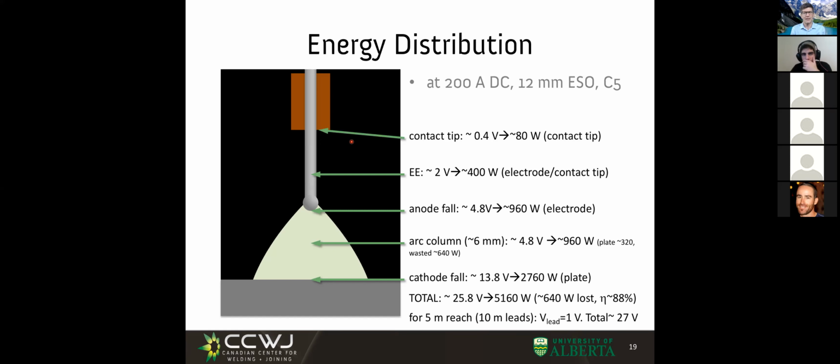We start having an understanding of what's going on, right? And stick out, especially in steel, is a very unfairly dismissed welding parameter. People know the current, people know the voltage, people know the wire feed speed. But you know what? In steel, if you don't tell me the stick out, you're giving me insufficient information. I'll show you how much that matters.